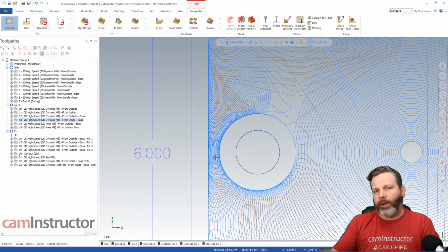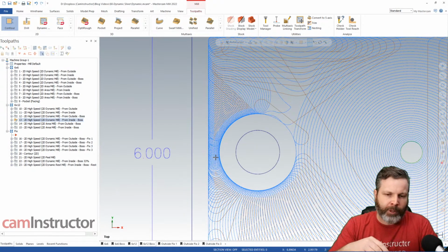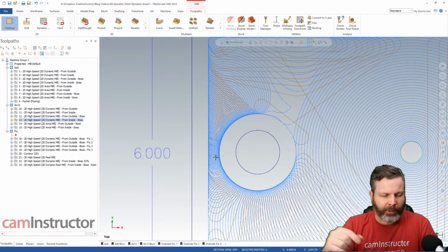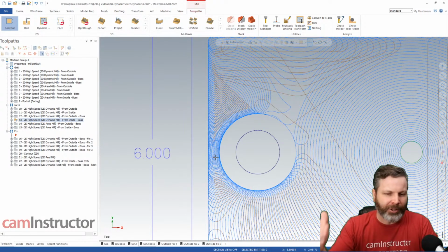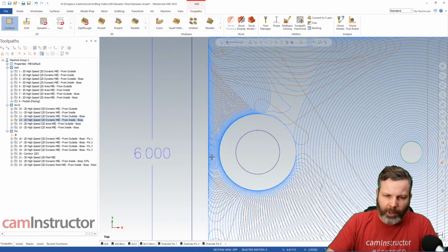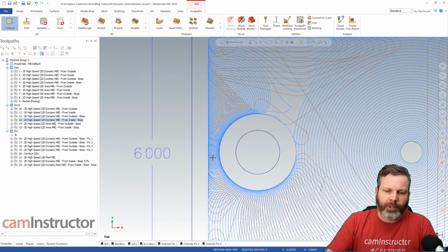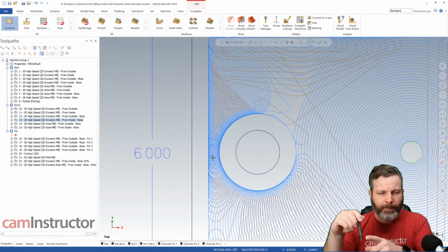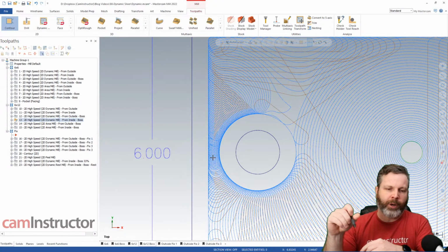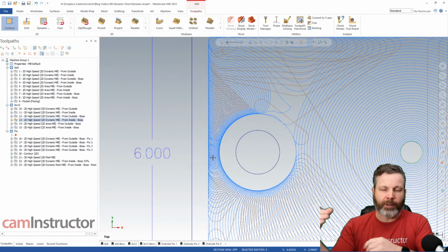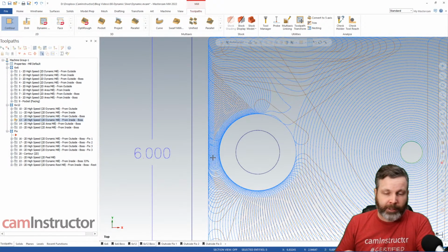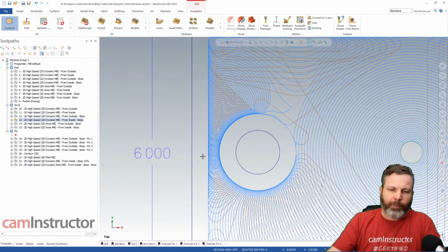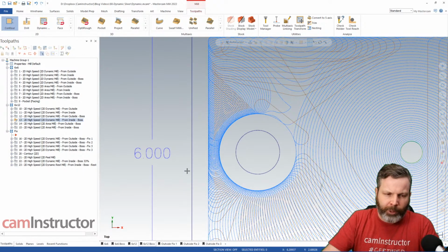But if we take that down to the other extreme and we're talking a 1/8 inch end mill, and we're getting into a very, very small scenario where maybe 10 inches per minute was pushing that tool to the limit, and we're getting into very tiny arcs where we're exceeding the recommended chip load by 10 times, yeah, you could easily break that 1/8 inch end mill. So how do we address that? All right, let's get into that.